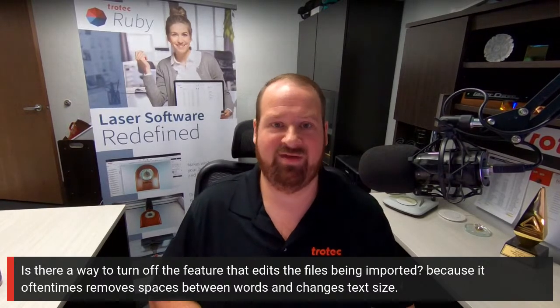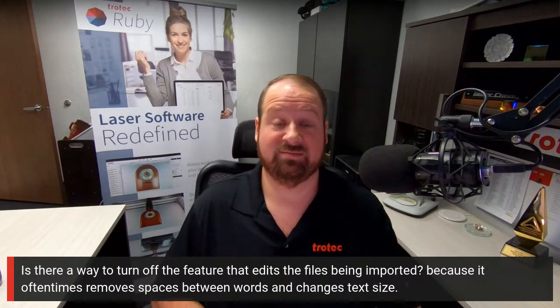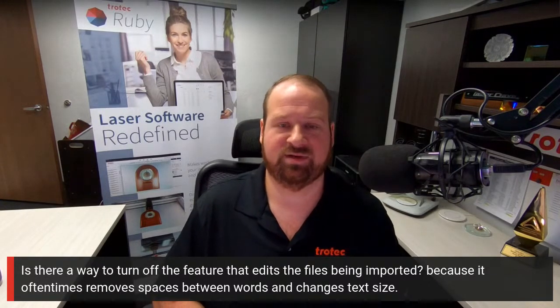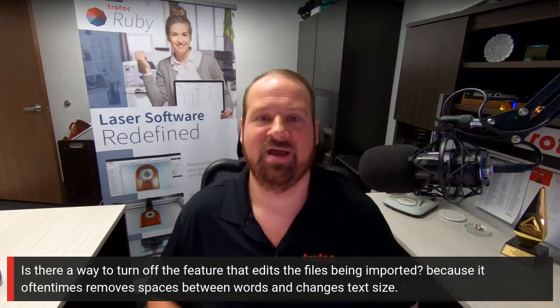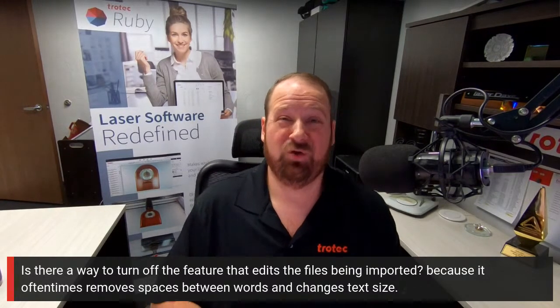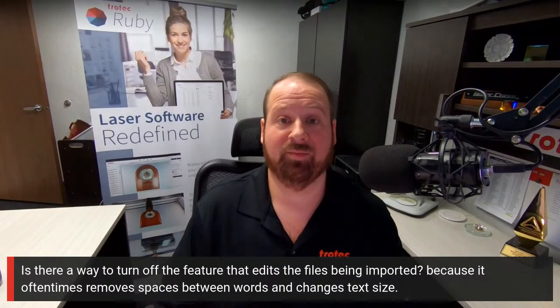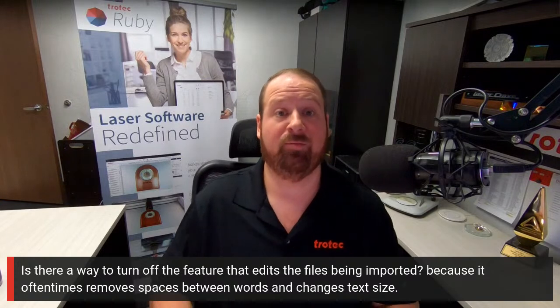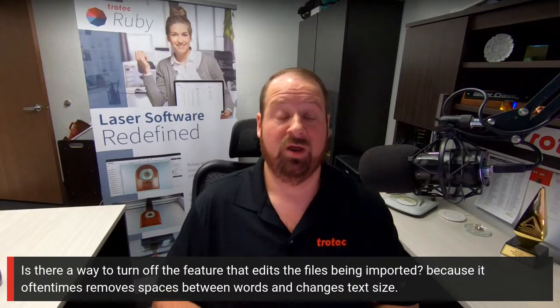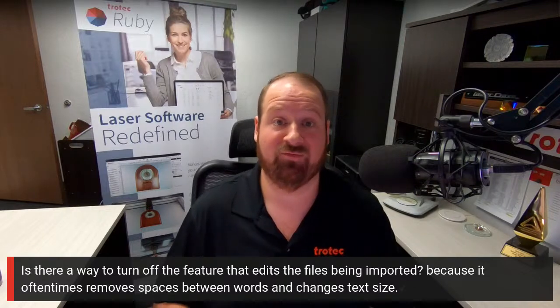This is why they've added the font feature. So for example, if the font comes in incorrectly, a lot of times it's because it's substituting a font. And in that case, you want to make sure that font is done. If you do run into strange occurrences once in a while when importing a file, try a different format. Try the more generic formats to be sure. For example, the SVG or the PDF are going to be your most generic formats.